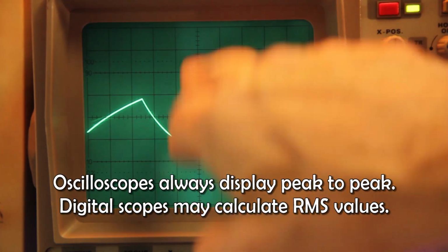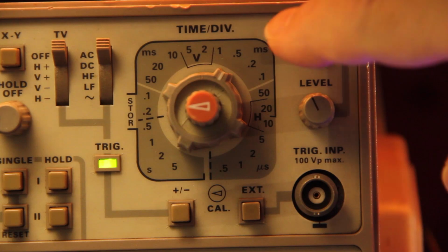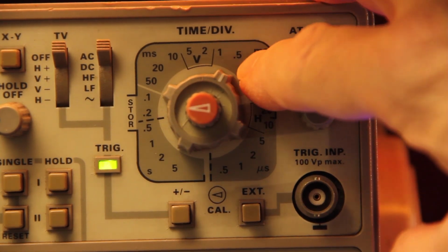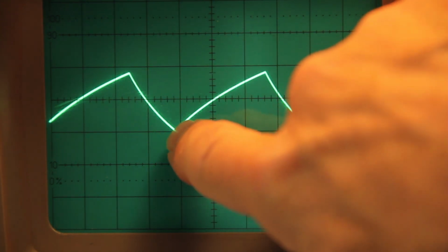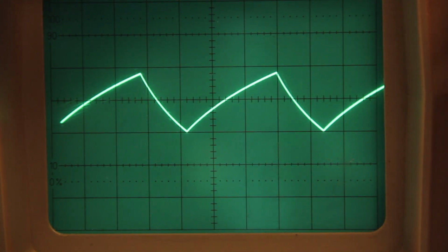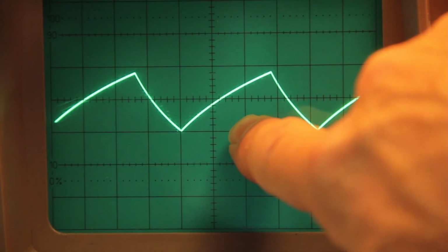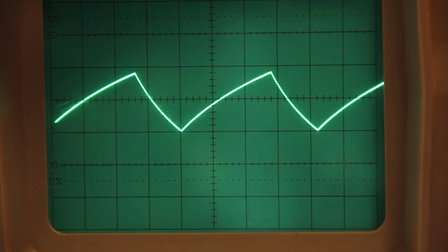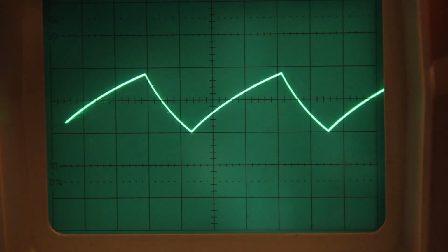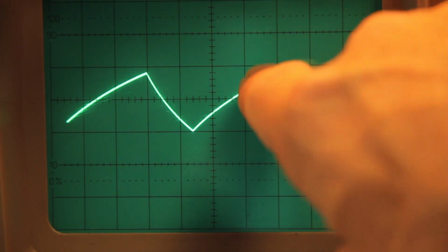This is on the y-axis, while on the x-axis we have 0.5 milliseconds per division, or 500 microseconds per division. So between this point and this point, let's align a little bit better, we have 1 millisecond, a little bit less than 1.5 milliseconds, and the full cycle is about from here to here, which is 1, 2, 3, and 4.